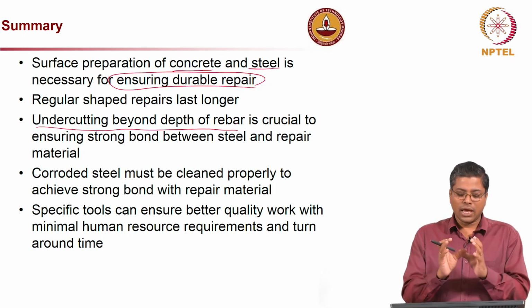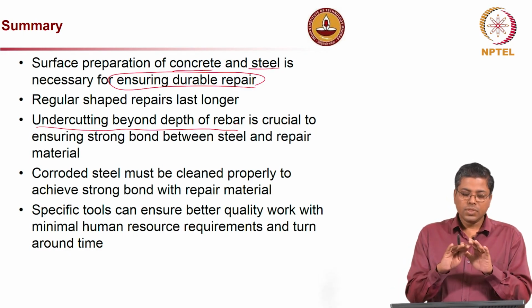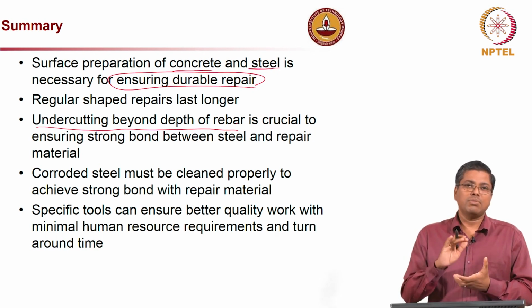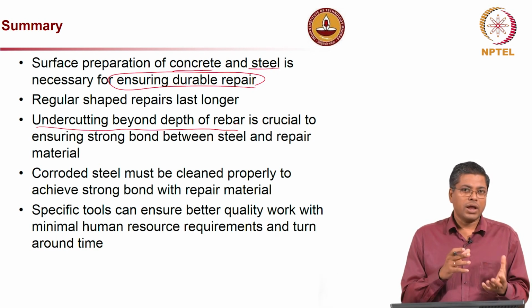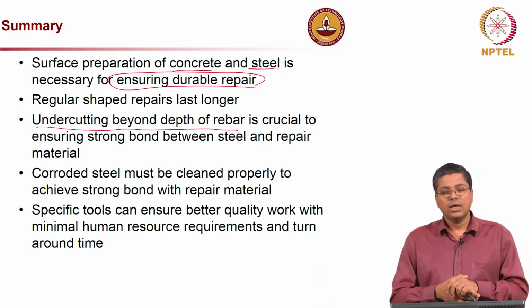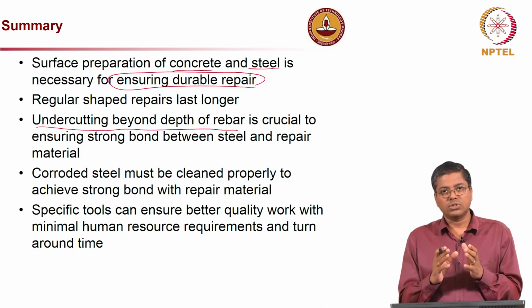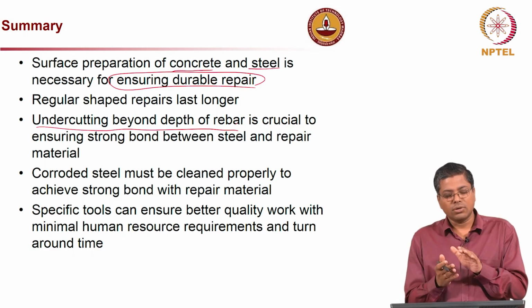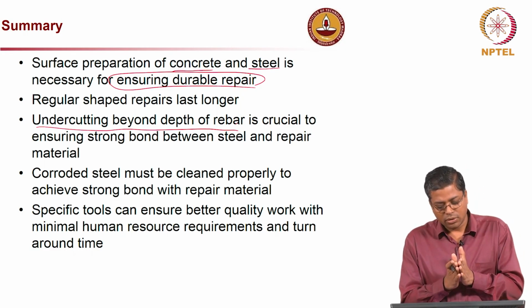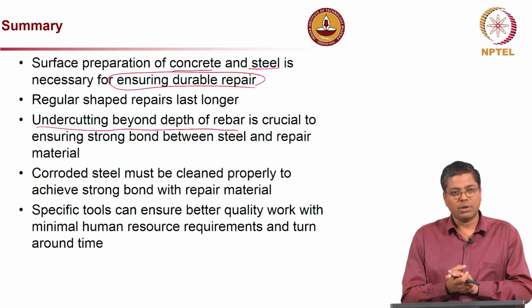At the same time the full circle of the rebar will be exposed to the same repair material, so that you do not have any potential for a corrosion cell to develop. In other words, no steel surface should be exposed to both the old or substrate concrete and the repair material.